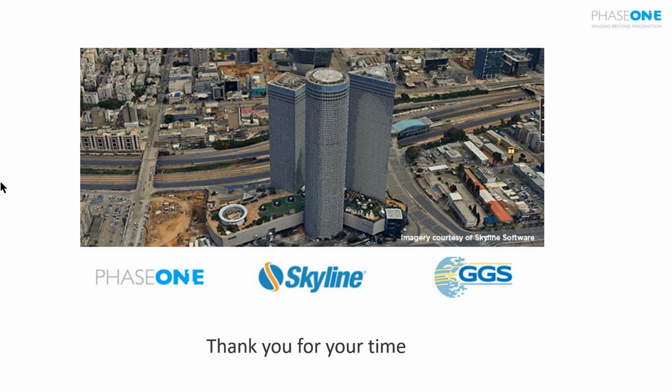The LiDAR can be used to extract control points. You can use the LiDAR intensity to sample features in the LiDAR, like markings on the road, which I showed was a survey point, that could be a LiDAR point. So you could improve the accuracy of the images by extracting control from the LiDAR, but it doesn't automatically assist in computing tie points.